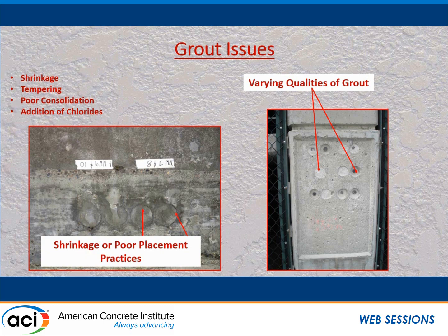It shouldn't be that difficult to pack a dry pack non-shrink grout in, because of the shape and depth of the stressing pocket. On the far right there are some beams at the ends. This isn't a great representation, but it was the best photo I had.